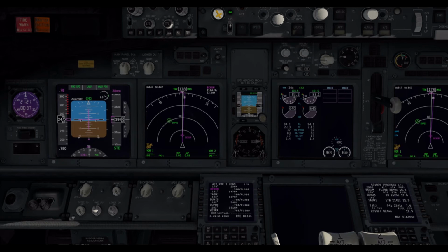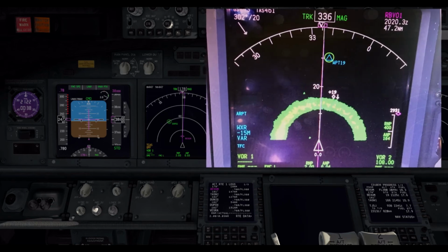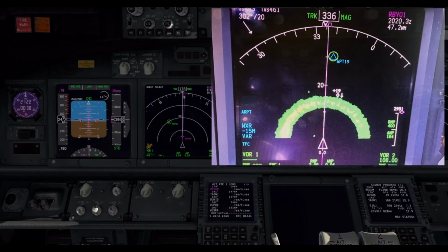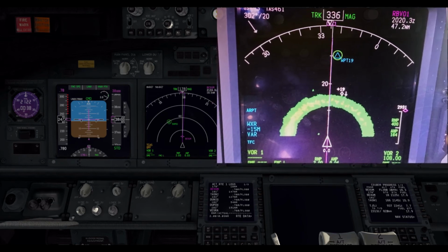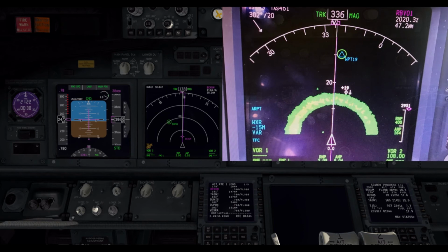So you'll see using this technology will significantly expand the safety envelope for all overwater flights, since you no longer need to see the ship you're ditching by. We discovered using the onboard weather radar in such a manner where we could easily paint ships on the ocean with incredible accuracy and detail. Since all of our test flights were used without internet service, this allowed us to physically verify the accuracy of the AIS data, the ship location data we were downloading.